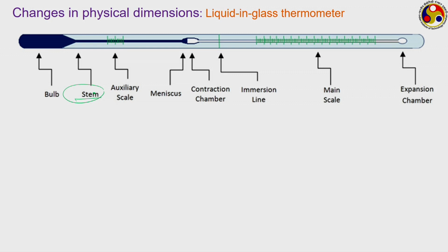And also, the void portion, like here the dark portion refers to the liquid you are operating with, and the empty void portion of the stem does not contain any liquid at this particular moment. It should be pressurized by a certain kind of medium, so that it can avoid the column separation of the mercury column and also avoid the vaporization of the fluid inside when the temperature increases.